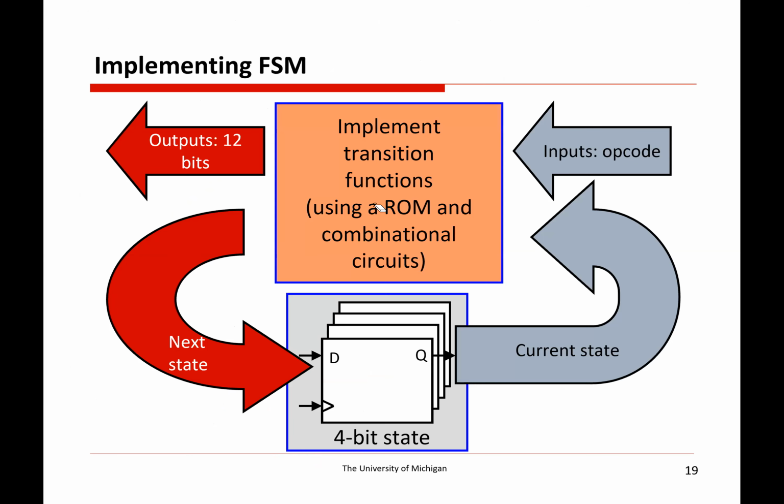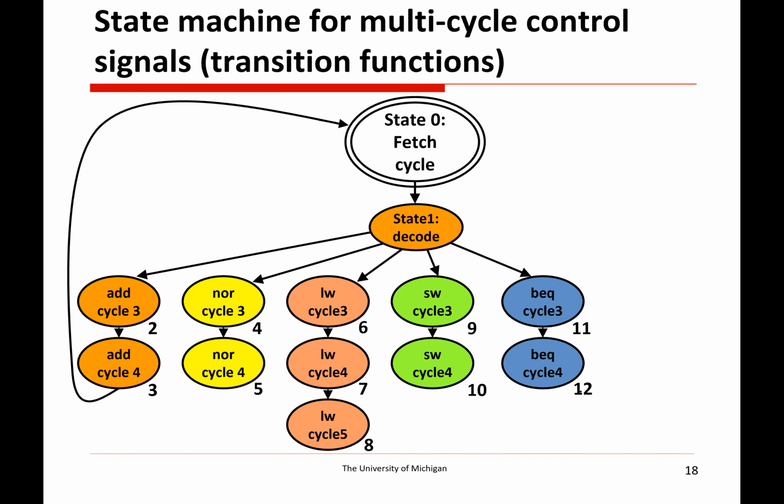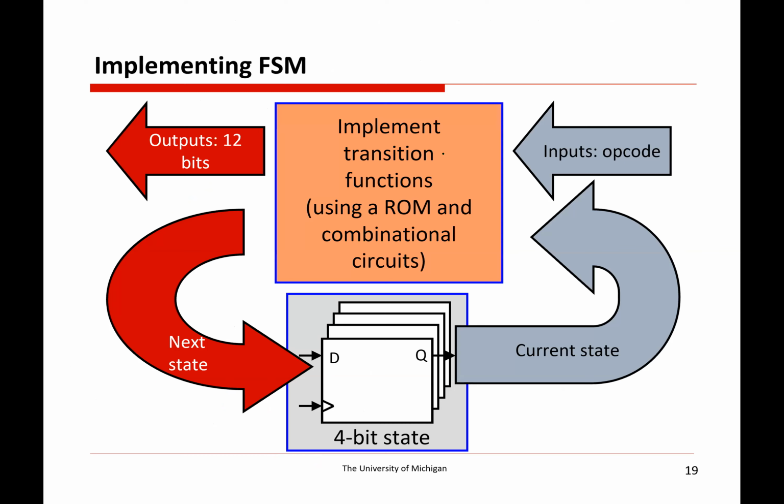Okay, and so now we're back to our old diagram from before. We need to implement this finite state machine. I have 12 states here, plus 0 is 13 states. Log base 2 of 13 would be, what, 2, 4, 8, 16. So we would need 4 bits to get up to 13. We round it up to the nearest integer. So we'll need 4 flip-flops, 4 bits of state in order to keep track of which of the 13 states on the previous slide I'm in right now.